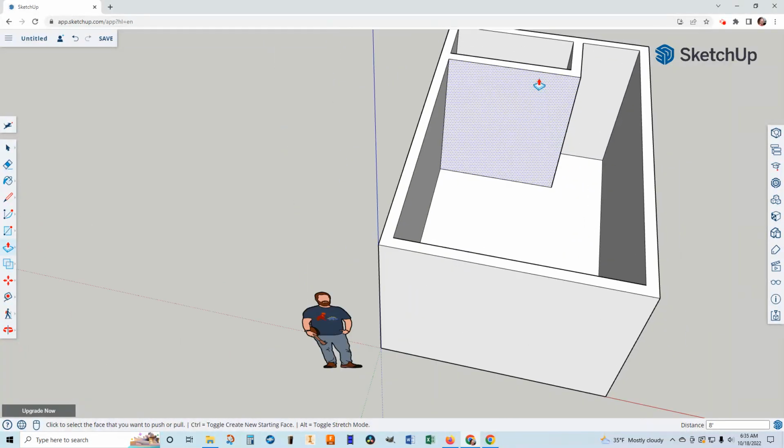Before I do anything else, I'm going to get a door into this closet since I'm looking at it right there. So let's go to the rectangle tool. Okay. And somewhere over here, make sure you're on edge down on the bottom. Don't start up here or down here, right on edge. I'm going to click once and move my mouse. And about here, I'm going to just let go of my mouse.